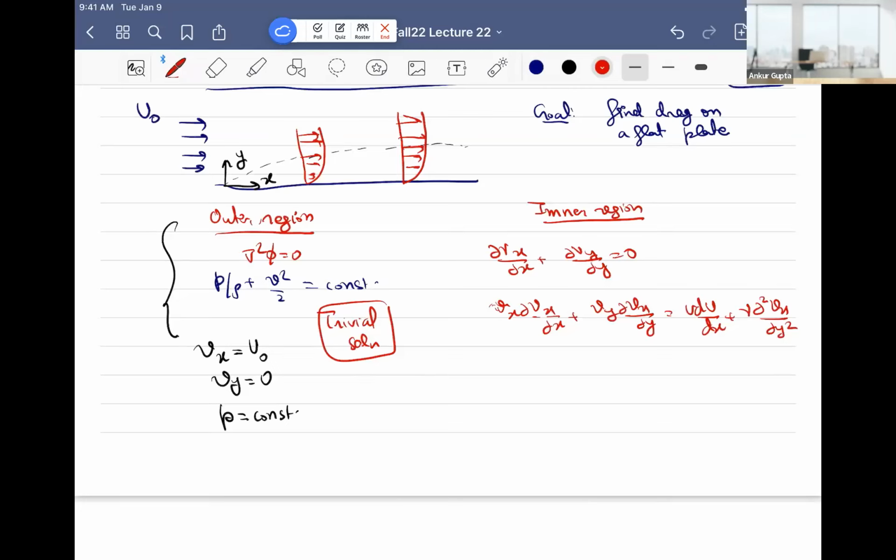The whole point here is that we have both vx and vy, but actually we cannot say that vy will be 0 inside. It can be a boundary condition, but it cannot be something you can say inside. But this u du by dx term, right? This u du by dx term comes from outside. This comes from here, right? So this comes from this vx of x comma 0 is u, right? And in this case, because it's u naught, everywhere it's u naught, right?